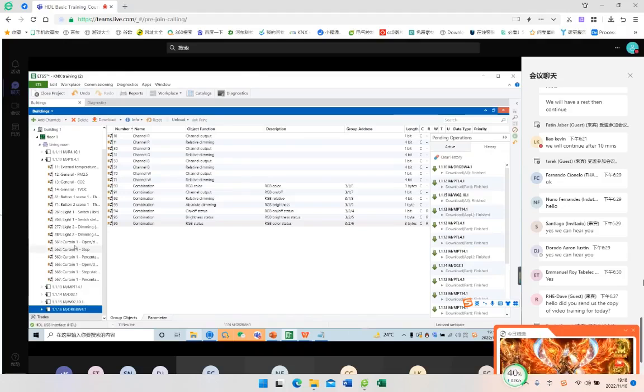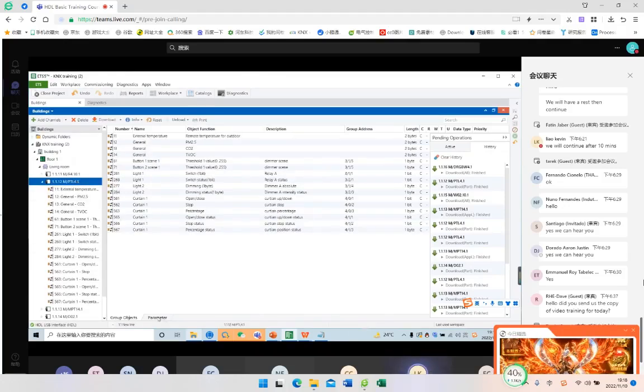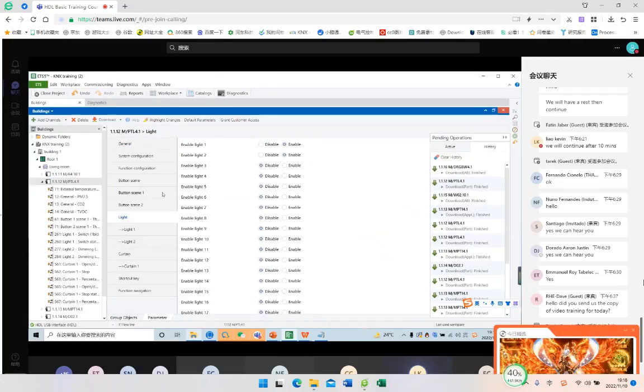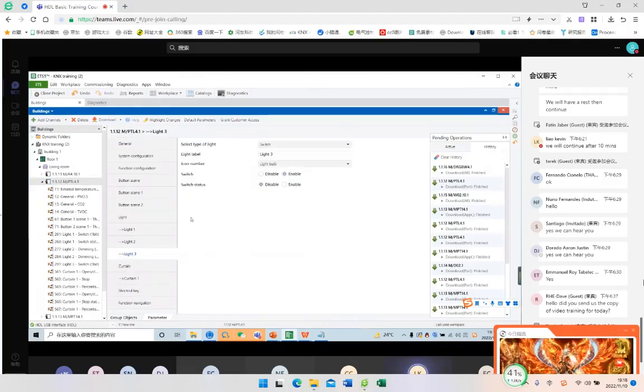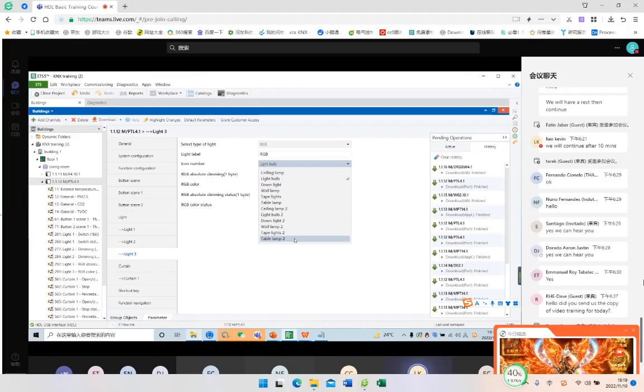And next, I go to the Granite display and go to the lighting page, enable light 3, and give a remark. For the type we should select RGB, and for the label we can use the name RGB. And from here we can select the icon, maybe this water lamp, and then we enable the absolute dimming and also enable the RGB color.